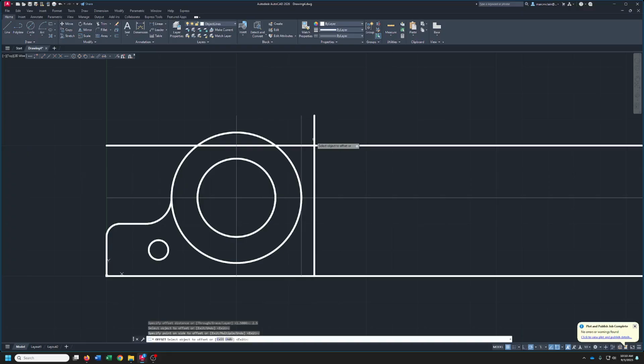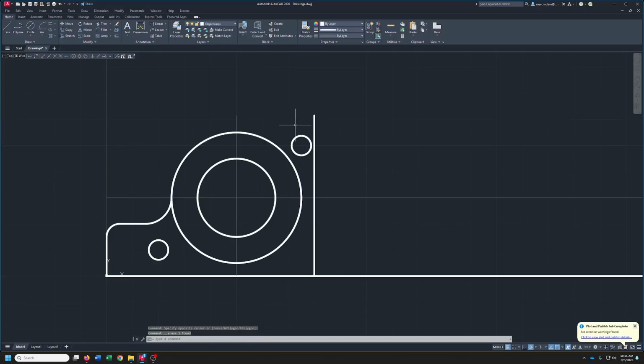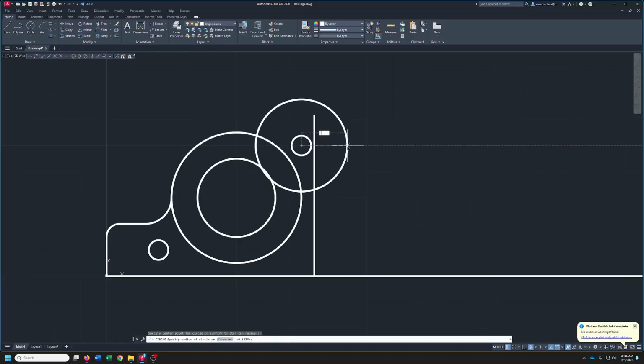All right, I'm going to have two circles centered there. One's a diameter of 0.375 and one's a radius of 0.375. Let's do the diameter first. Right here, 0.375. Now I'm going to take this out and this out because I got a center I can use now. Go get rid of these two as well. Radius. Same number, 0.375. And there we go.